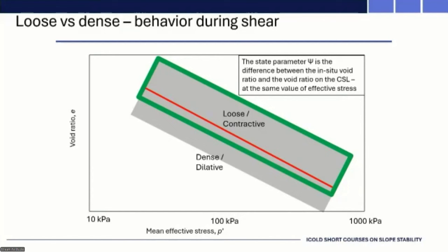Now, if you look at the Brumadinho video, and I don't know how many of you have lost sleep after watching that. I know I certainly did. I just thought that we have no idea what we're doing. But if you watch how that failure propagated, you had that initial event near the bottom of the slope, and then within seconds, you had the slumping and the failure propagating to the top of the slope. I think that material would have been at such a high state parameter that as you tipped it over the edge,